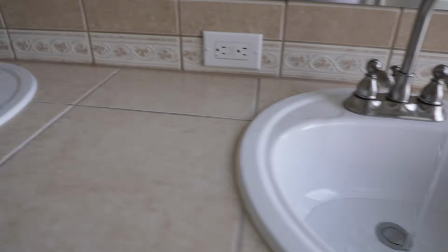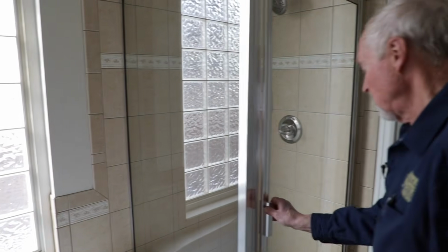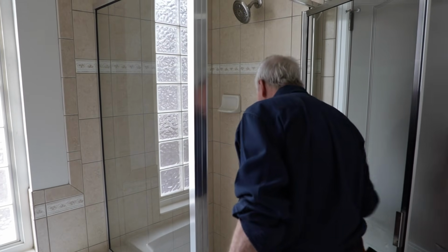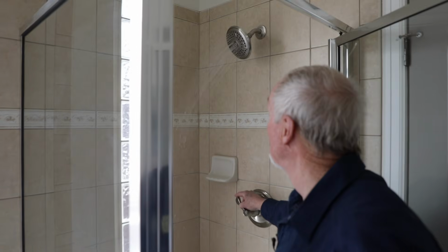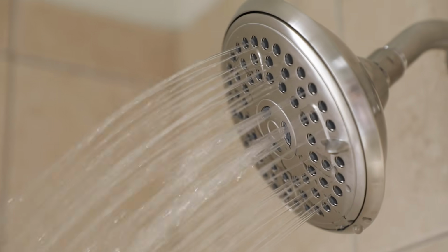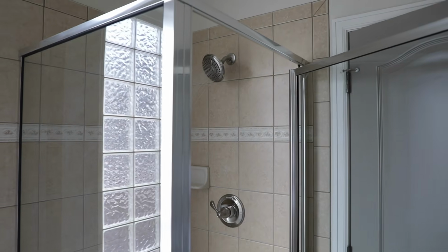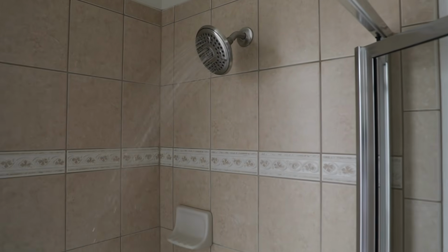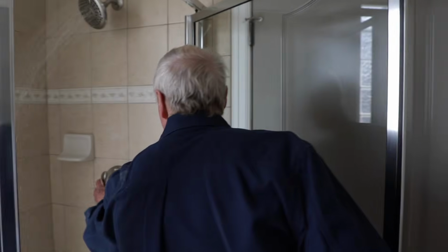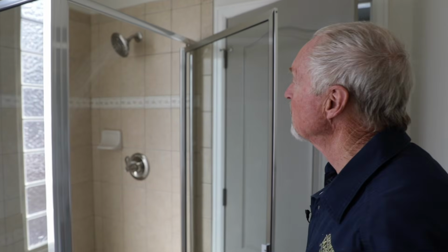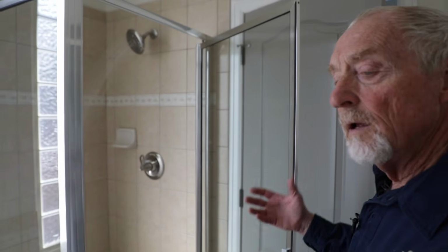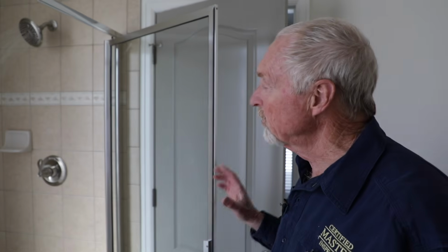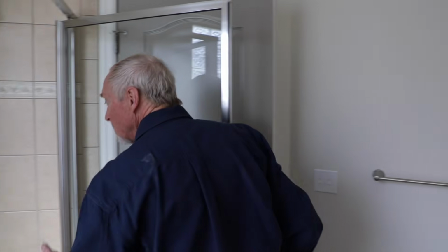Also, I'm going to turn my tub back on quickly here and run my shower and see if I get a decent flow of water on my shower. I have a little loss of flow there. I'm going to turn this off. We'll see how much it improves if I turn these off. Not a big difference. I don't have a concern here because even though that's not exactly a hard shower and may have clients say something about it, it's not an issue with too many fixtures running. It's just an issue with the individual shower head here.